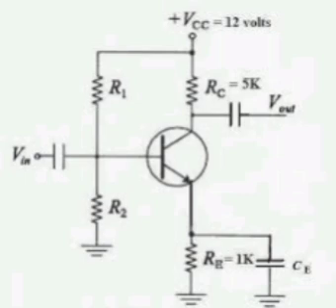Prove that true power equal to cos phi by cos beta into cos phi minus beta into actual wattmeter reading for electrodynamometer type of wattmeters, where cos phi equal to power factor of the circuit, beta equal to tan inverse omega L by R, where L and R are the inductance and resistance of the pressure coil of the circuit. Next question, explain why errors are large when the power factor is low.